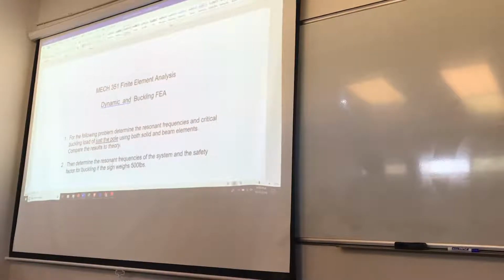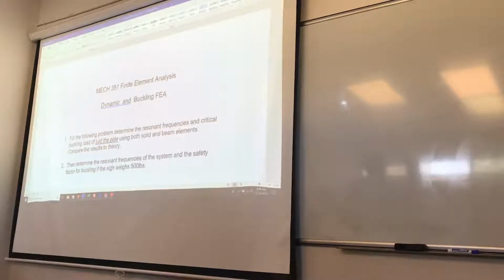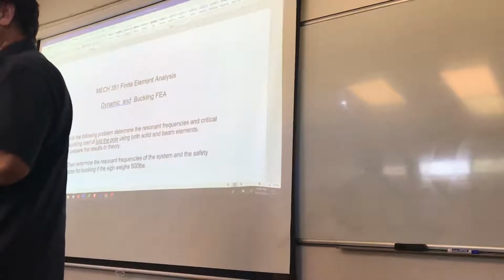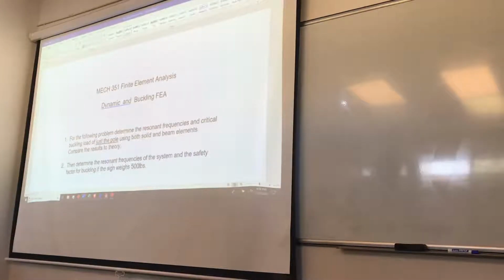Stability analysis gets coupled with frequency analysis, because it's easy to do. They're both basically modal analysis, that is, they're assuming a shape, and the analysis will give you which frequency things will vibrate at.